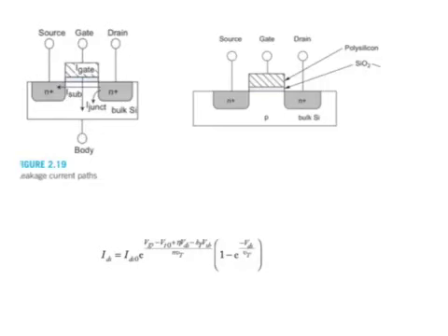Leakage currents in short channel MOSFETs are another source of concern in modern digital design. Leakage currents refer to current flows that are not associated with useful or work-related switching, that is, switching that's associated with computation of logic, but they are background flows of currents due to non-idealities in the device.